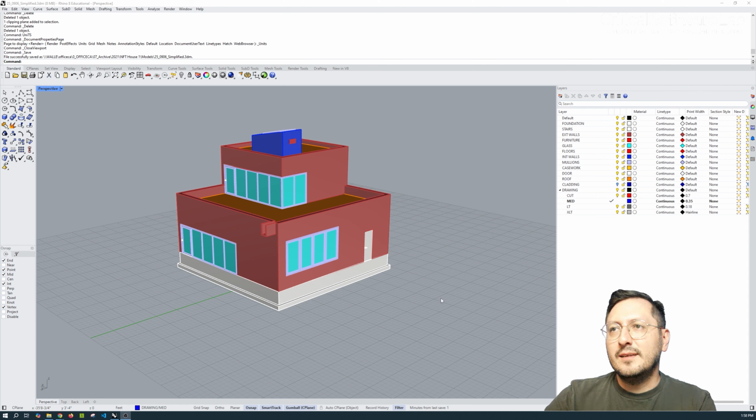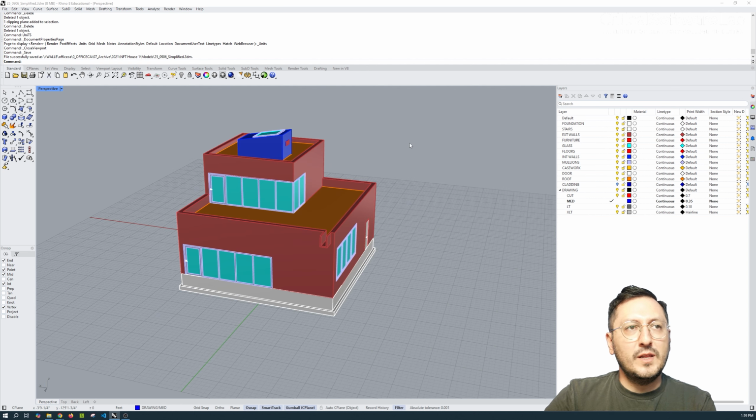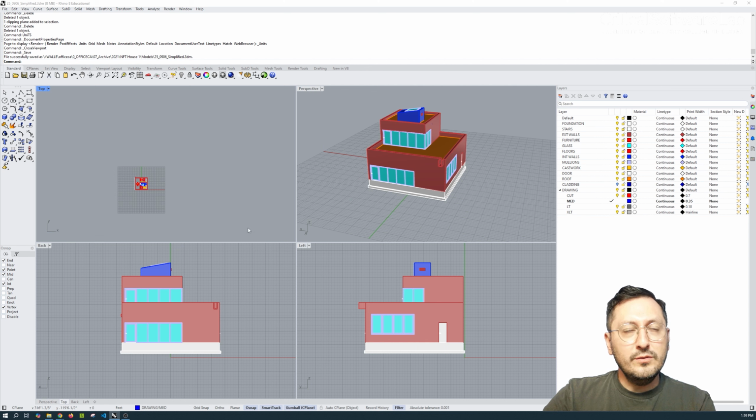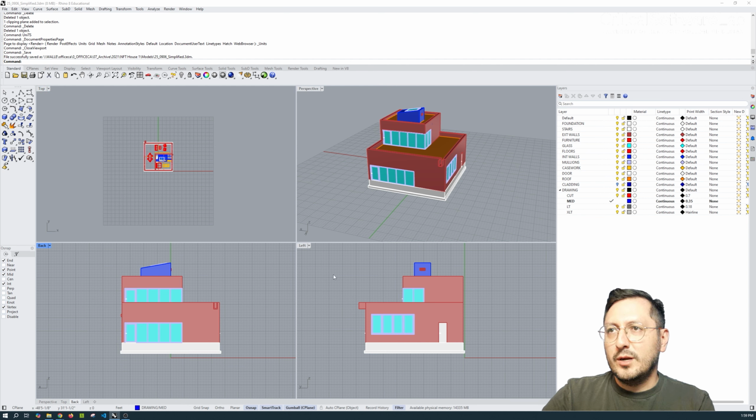With all of that in mind, let's start making orthographic drawings in Rhino. The first thing that we have to think about when we're in Rhino is that our viewports are essentially picture planes, where all of the lines and colors are coming together and represented as a flat 2D image that's on my screen. Now the default viewport in Rhino is the perspective viewport, and the other viewports that we see here are orthographic, right? So the top viewport is a flat 2D representation of the world that I'm looking at in Rhino. The back viewport and the left viewport are different side views.